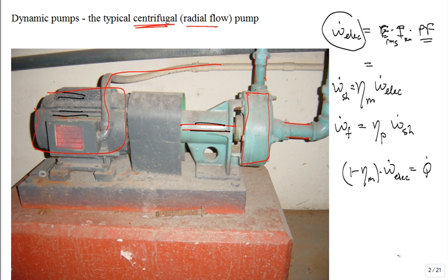All right. Then also, where does this 1 minus the pump efficiency times W dot shaft go? Well, it basically goes into beating up the water like an egg beater. So this gets into the water. Typically, the water flow rate and the specific heats are so large, you really can't measure a delta T of the water. The temperature difference is so small.